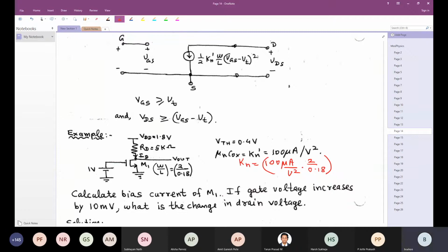You guys have already done this. So let's get one of you to suggest how to solve it. Make the saturation assumption, and we know that VGS is a constant and it's equal to 1 volt. Find the value of ID, then just confirm if VDS is actually greater than VGS minus VT. Okay, good. So yeah, I hope everybody got that.